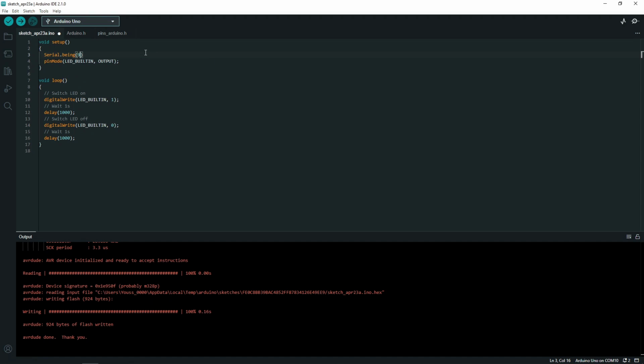The first thing you need to do to set up the serial communication is type in Serial.begin. This is to initialize it. There's something called the baud rate, which you specify, which is the speed at which it communicates. There are a few standardized baud rate values that you can use, but all this doesn't matter really. 9600 is a common one to use. So Serial.begin(9600), and then you can start actually printing stuff.